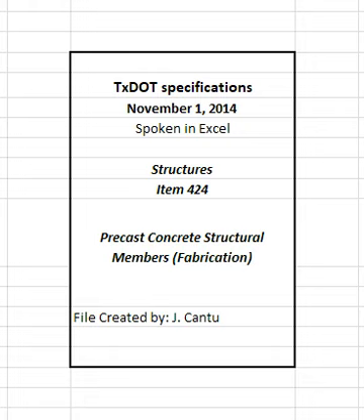Release the hold down anchor slowly to minimize shock and damage to the concrete member when draped strands are used. Heat the anchor until the metal slowly elongates and gradually loses strength if heat is used to release the hold down anchor. Provide positive external hold downs to offset the vertical forces in the members when the sum of the hold down forces is greater than half the weight of the member or for any amount of vertical force that has previously caused cracking. External hold downs are to remain on each member until detentioning has been completed.